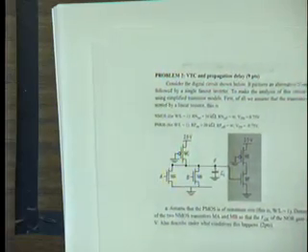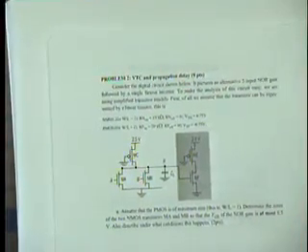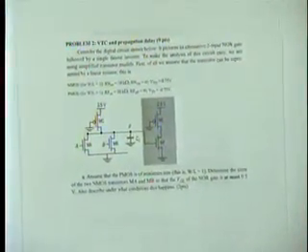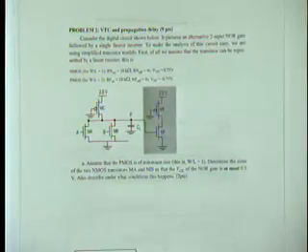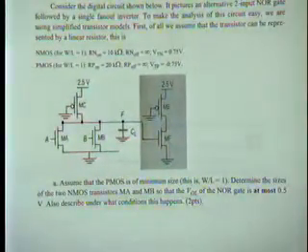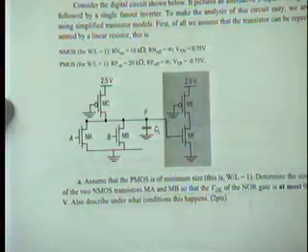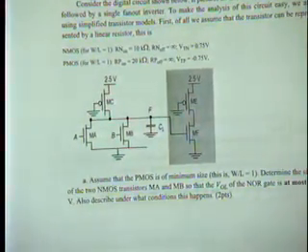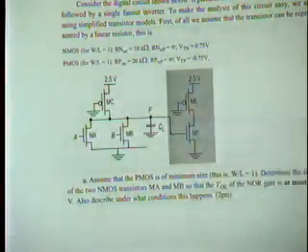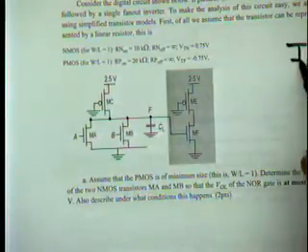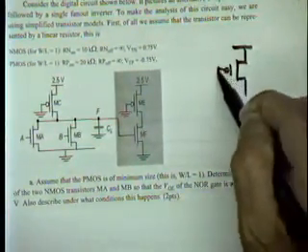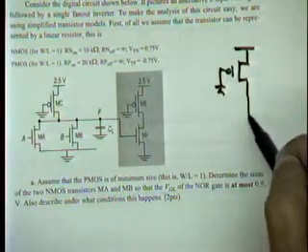Okay, this question is a little bit more relevant. This is a question where we have two gates in series with each other. It doesn't matter if this is an AND gate or a NOR gate. It's perfectly legit in terms of the coverage of this thing. It's just looking at certain interesting questions to be answered. So this is an inverter. One of the other types of inverters not using an NMOS, but uses a PMOS, which is grounded, as the load device.